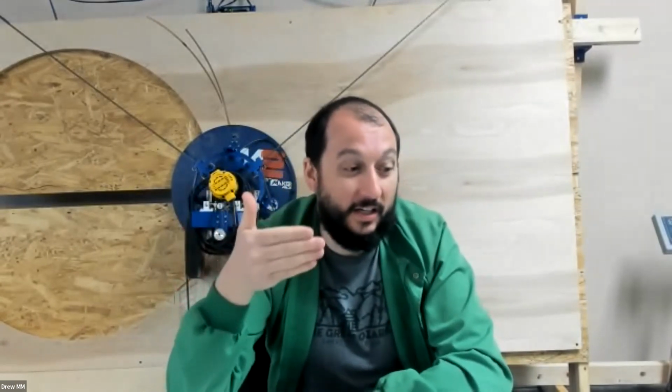Then you want to make sure that your work offset doesn't have any numbers in it and is at 0 too, because it might think that the bit is a little above your surface. Then it starts cutting above and isn't cutting anything. Does it ever move and not cut anything? Yeah, sometimes it does. So I bet that's it. I bet it wasn't set to 0 on your work offset. You can see those here. Let me share my screen with you real quick.